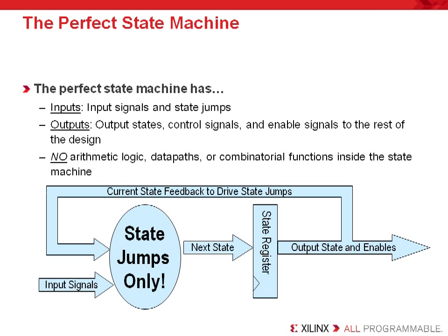When this happens, there is less logic to create timing critical paths. Remember that most designs that include finite state machines find timing critical paths that pass through the state machine itself. Careful consideration of the design of the finite state machine is not only good for speed, but also important for building a reliable FPGA design. This is because finite state machines often will expose glitches and ground bounce problems designers build into their FPGA design.